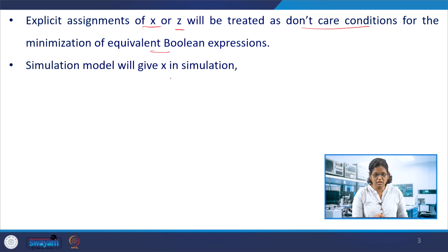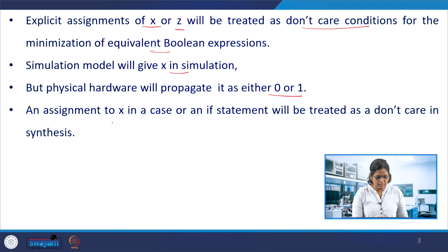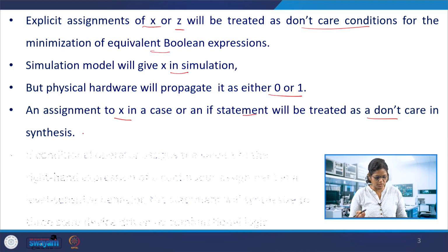The simulation will give x, but in hardware it is either 0 or 1. So, the Verilog code shows x in the simulation, but in the hardware it should take either a 0 or 1 value. In that case, the assignment to x in a case or if statement will be treated as don't care for the synthesis process.